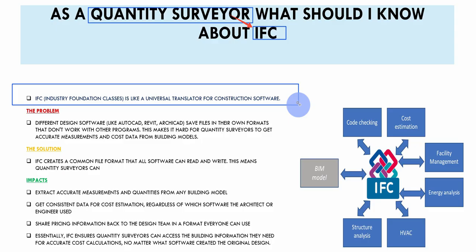For you not to fall into that mistake, you might be required to have the skills of a translator, an IFC reader. Then you require the designer, or whoever did the project in any software, to translate the project package, the model, into an IFC. When you receive that as an IFC format, as a QS, you will be able to visualize and see all the information in that project.